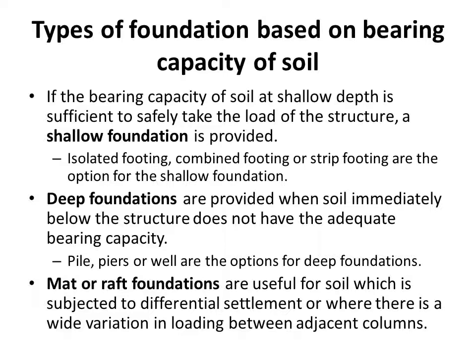Now let's see the different types of foundations based on bearing capacity of soil. If the bearing capacity of soil at shallow depth is sufficient to safely take the load of a structure, a shallow foundation is provided. Isolated footing, combined footing, or strip footing are the options for shallow foundation. This type of foundation is mainly provided in soft rock or gravel.